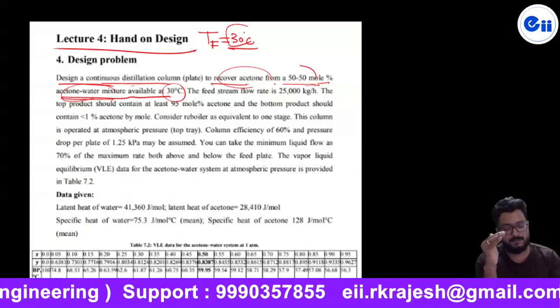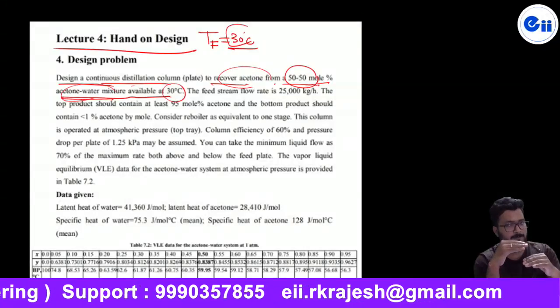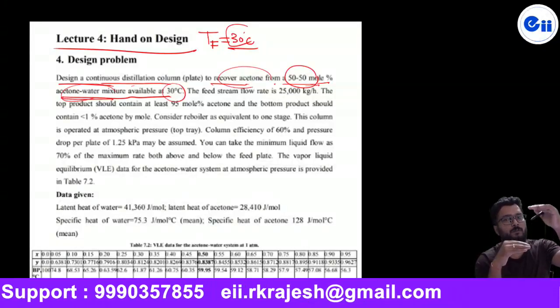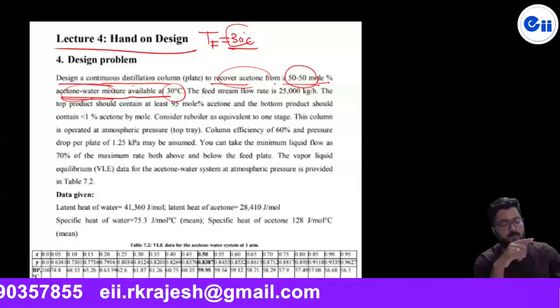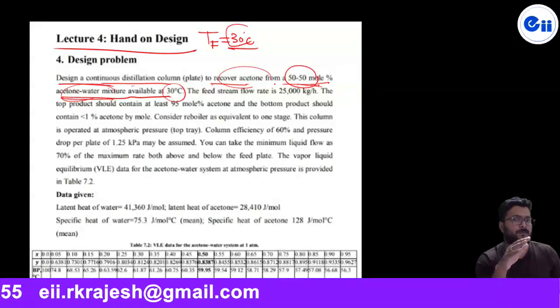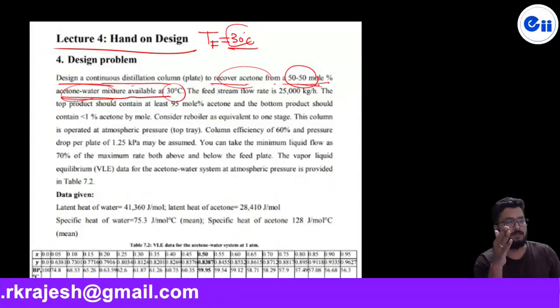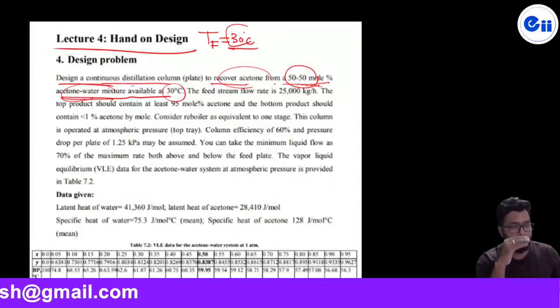with the same composition, because as we start heating the feed up to the bubble point, there is no change in composition. Composition will change later, as I showed you in the boiling point diagram, if you recall. When the feed temperature is lower than the bubble point temperature, the feed is a cold liquid. If it is equal to the bubble point temperature, it is a saturated liquid.